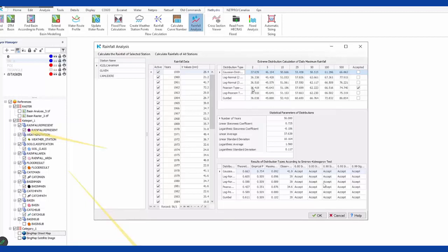So you can consider those numbers in terms of years. So in 2 years, expected rainfall is 36.4 millimeter. In 5 years, there will be definitely 45 millimeter rainfall or something close. And in 10 years expected to happen is 51. So yeah, it goes on. According to that information, later on we are going to calculate the flow, and flow will help us to understand what would be the sizes of the structures that we have to decide.